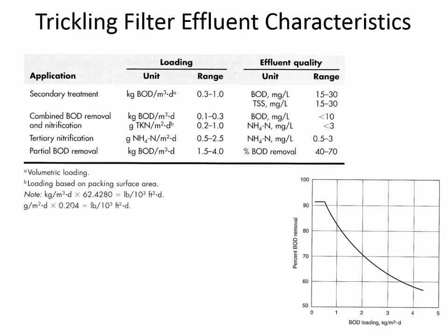organic loading rates compared to the higher organic loading rates, where you have a high loading rate, there's going to be less removal. And this little flat part of the curve says that once you get to a certain point, even if you decrease the loading rate lower and lower, you're not going to have any further improvement. That there's an upper limit to the removal of BOD through a trickling filter.